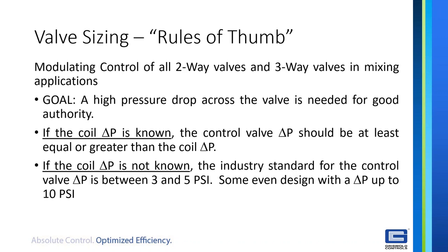Well, by design, our valve actually, as we talked about last week in our balancing, the automatic flow limiting valve, when it's reducing below full flow, drops off so that the pressure differential drops, so that you have that cooperation. So you want the control valve at reduced load to have authority so that it's what's controlling the flow in the system.